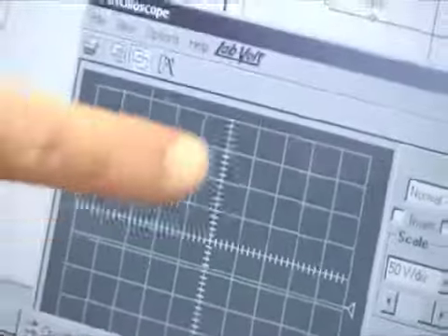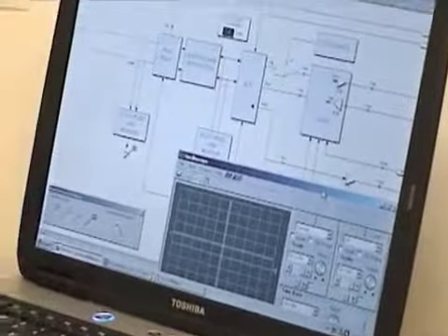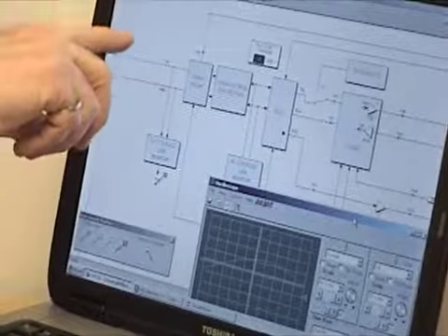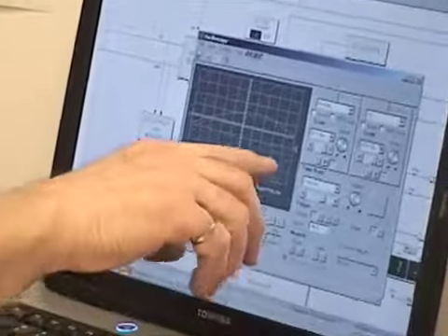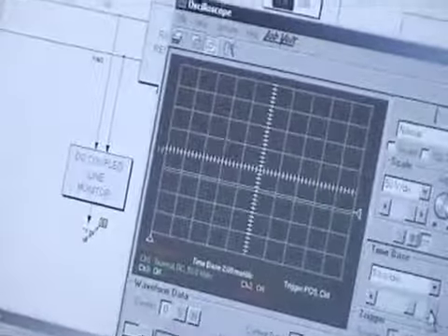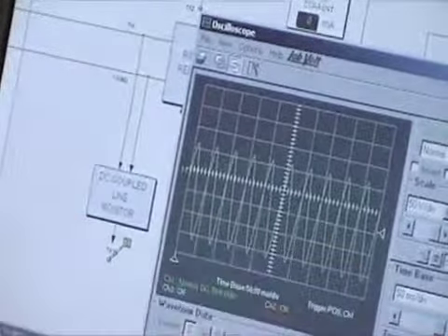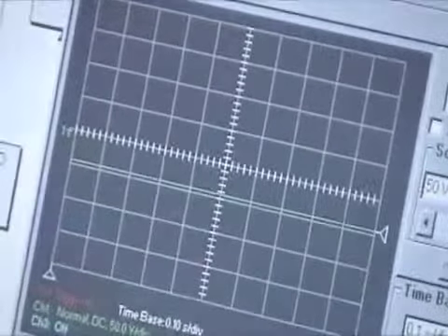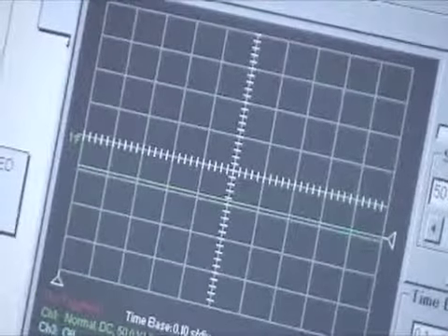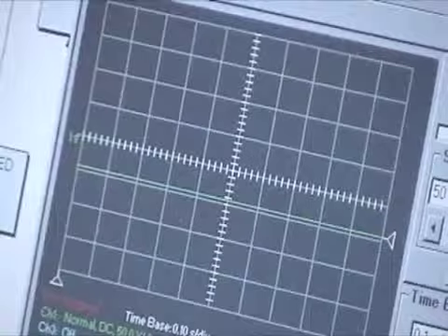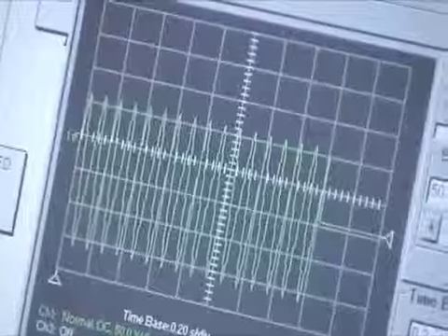So what's happening is the central office had a call coming in that wants this phone, so now it puts a ringing voltage on that phone. So basically what you're going to see is 90 volts plus or minus sitting on the minus 48. And let's see if we do see that. There's the minus 48, and we're going to be able to see the ringing voltage. There it is, sitting right on top of that minus 48. So you can see it again. There we go, and there's minus 48 and the ringing voltage, plus or minus 90 volts from that.